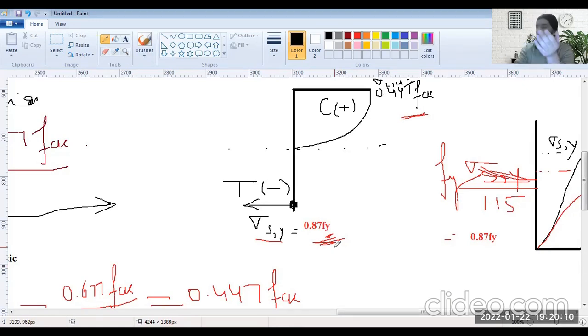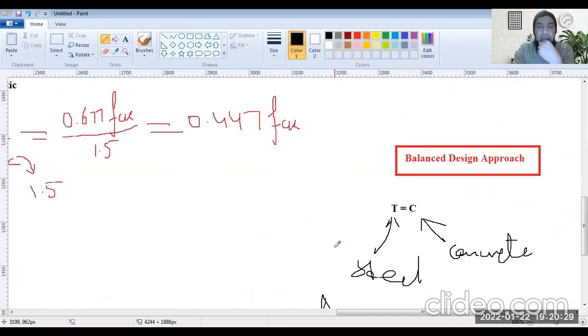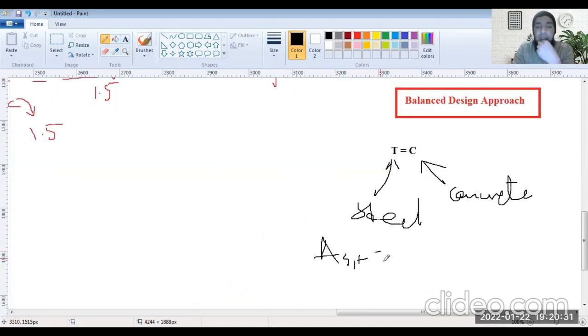Why? Because if you have a beam and this is the steel bar in the beam, the load comes on it like this. So what will take the load? It will be the cross sectional dia. The thicker the steel bar, the more tensile force it will resist. So the cross sectional dia is taking the tensile forces. So AST is the area of cross section of all bars in tension.